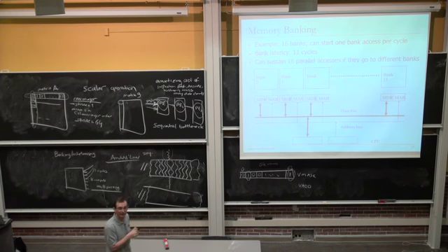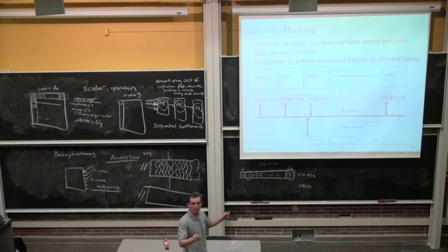Yes? How do you store it in different banks when you actually store the vector? How do you store it in separate banks? So it's the same thing, right? You store the first word in the first bank. You store the second word in the second bank. Third word in the third bank. Again, the vector store operation is pipelined. In consecutive cycles, you store to consecutive locations.